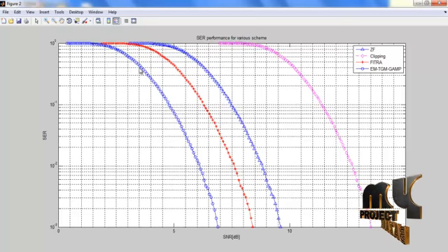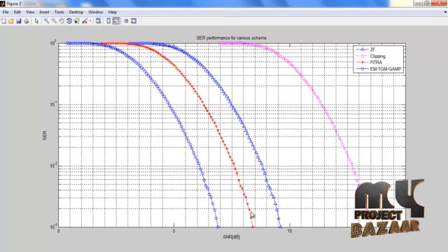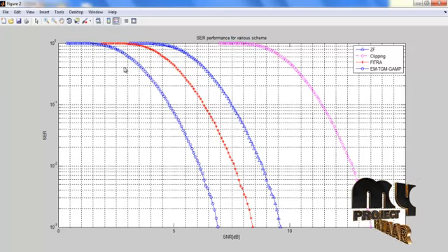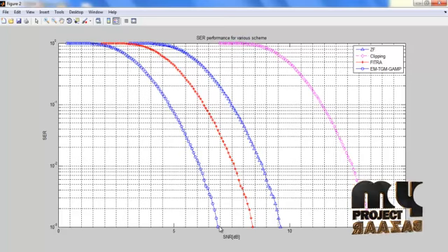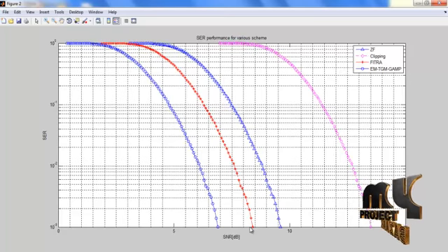Now the graph shows the values of EM, TGM, GAMP, our proposed system, and the values of FITRA, fast iterative truncation algorithm, and zero fading and clipping. The graph shows that our symbol error rate value decreases as the value of signal to noise ratio increases. From our proposed model, we are able to analyze that our proposed model has the least signal to noise ratio value compared with the zero fading, FITRA, and other algorithm methods.